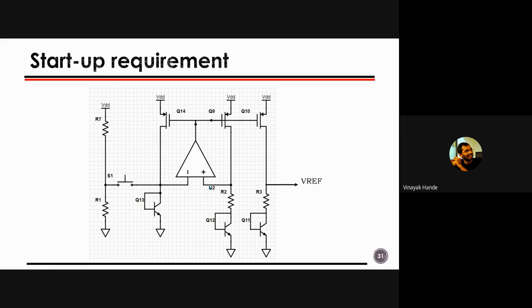So when you start the circuit and ramp your VDD while testing your chip, you will ramp it from 0 to VDD. That's generally the process. Even if you connect the voltage source directly, it is considered a step response, also a kind of ramping with t equal to 0, or delta t very, very small.